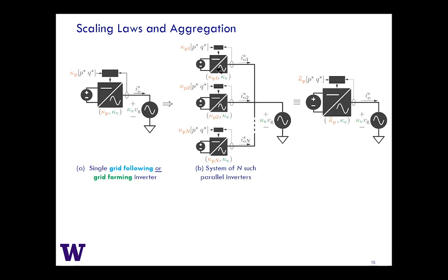I actually talked to someone at a manufacturer who makes large three-phase inverters, and he said that these scaling laws are very similar to how they scale their controllers. So they recycle their per unitized controllers in 100 kilowatt versions, 500 kilowatt versions, and megawatt scale versions. So it's very much in line with that, which brought me comfort to know that this does align with that.